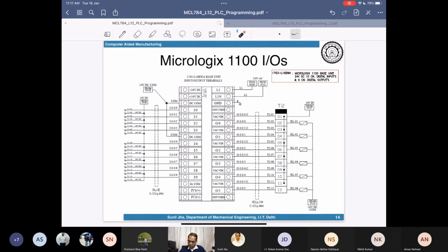What I just want to add over here is that we normally isolate the digital outputs. Inputs are fine, or you can also use a relay for isolation over here. So isolation through a relay is a very important implementation in all automation systems. When I say isolation, it means that I don't want any wrong signal to enter the PLC and damage it. When I say wrong signal, it's either an over voltage or a short circuit, something happening outside with the device; it should not damage the PLC inside. So that is how the isolation works. And isolation is done with the help of electromagnetic relays actually. So that is the component that you need to understand.